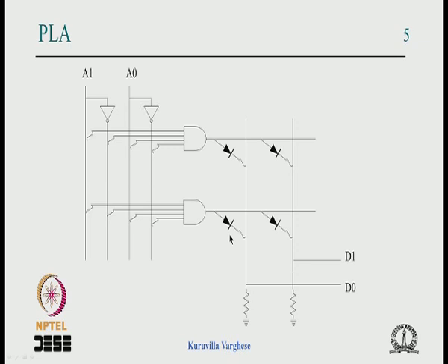Now this becomes pretty much complicated, because if you have multiple outputs, what to program and how to program this? When you have multiple outputs, it's possible that a single product term can be shared between the outputs. We talked a little bit about multi-output minimization in the overview at the beginning of the course.